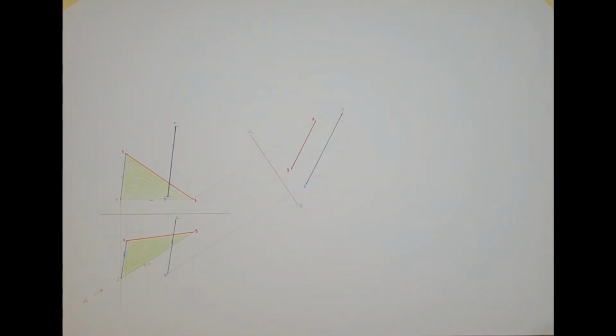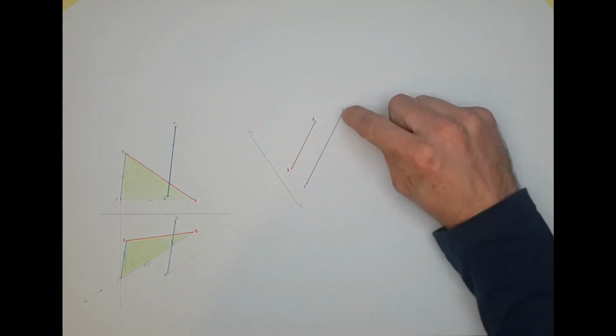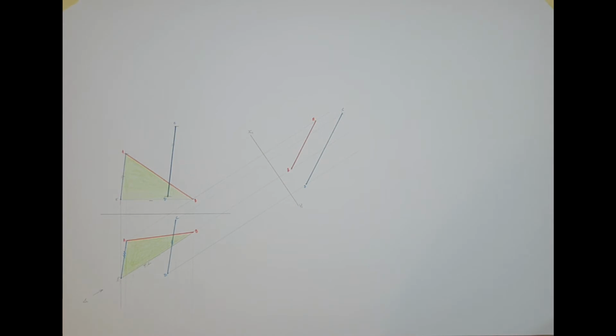That auxiliary elevation gives us a view which shows the two lines appearing as if they are parallel. That's the first step of this problem done. The next step, we'll go back to SolidWorks and we will have a look at it. Basically, there are 3 different ways the question could be posed from here, and we'll explore all 3, and we're going to try our best to get all 3 of them onto this question sheet here.